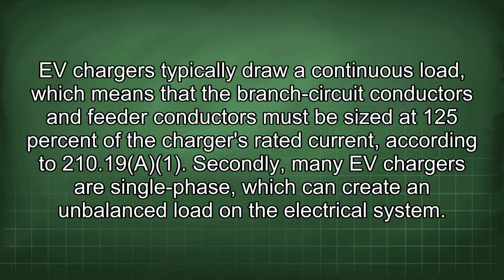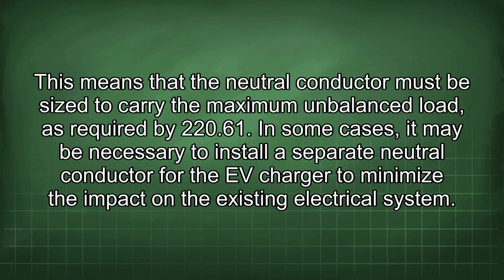Secondly, many EV chargers are single-phase, which can create an unbalanced load on the electrical system. This means that the neutral conductor must be sized to carry the maximum unbalanced load, as required by 220.61. In some cases, it may be necessary to install a separate neutral conductor for the EV charger to minimize the impact on the existing electrical system.